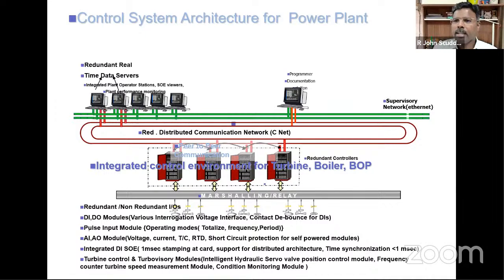Once you open any logic page, this particular field signal, this actuator's position, is coming into the DCS as a 4 to 20 milliampere signal, and presently it is 50% open. Everything is available in the engineering station. But it is not possible for operation engineers to access the engineering station and understand the logics, so we give it to them in graphical representations.